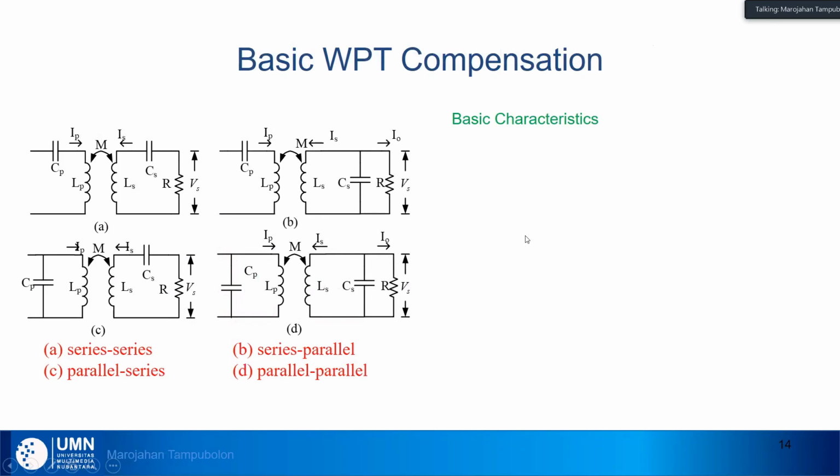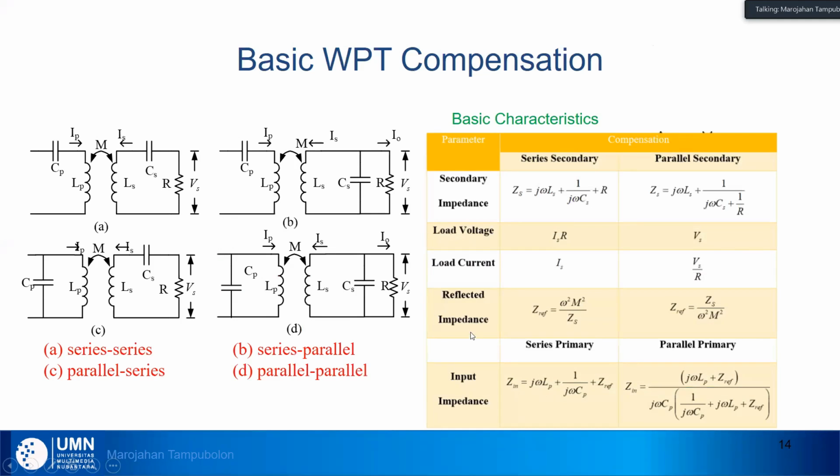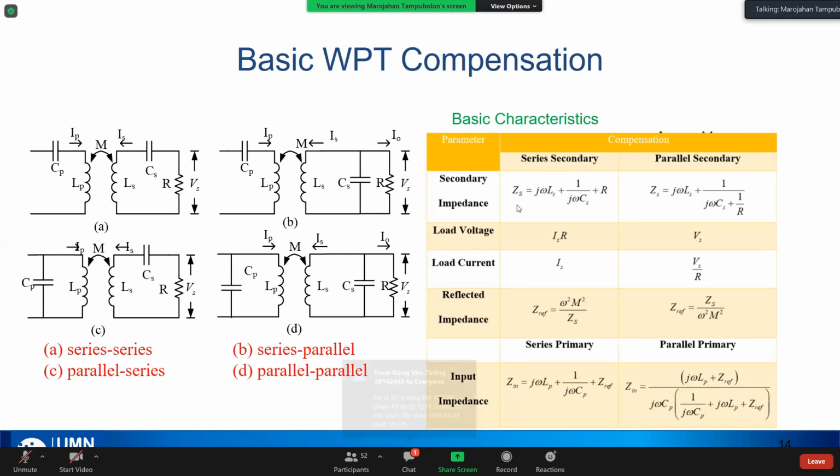Okay, the basic WPT compensations, we have here some pictures, and this is the basics. One is the series compensation, and then we have series parallel, and then parallel series, and also the parallel. And if we want to find the relationship here, like secondary impedance, load voltage, load current, reflected impedance, and input impedance, we can see it in this table.